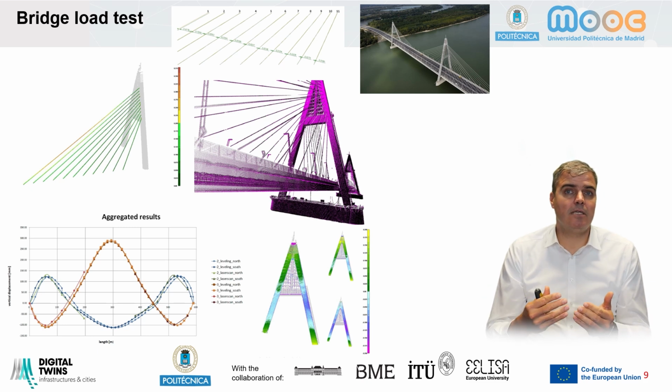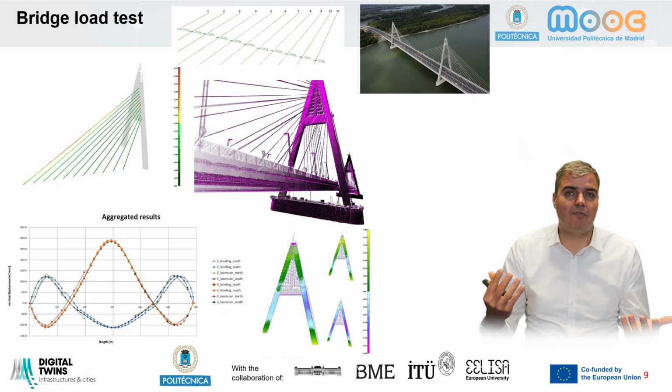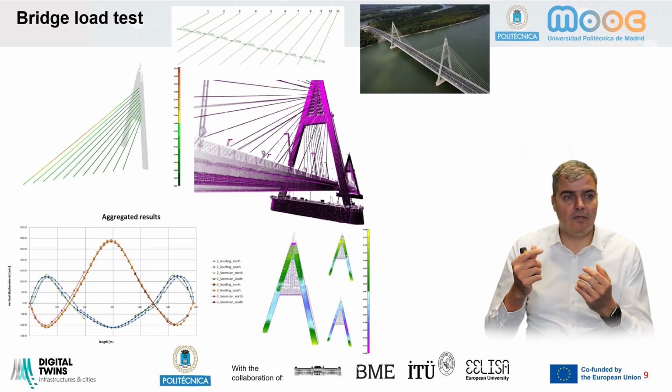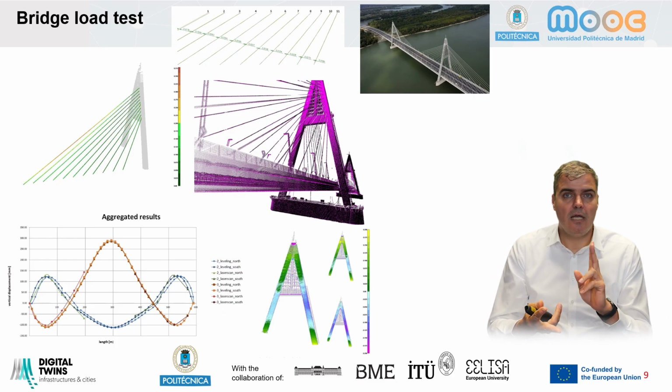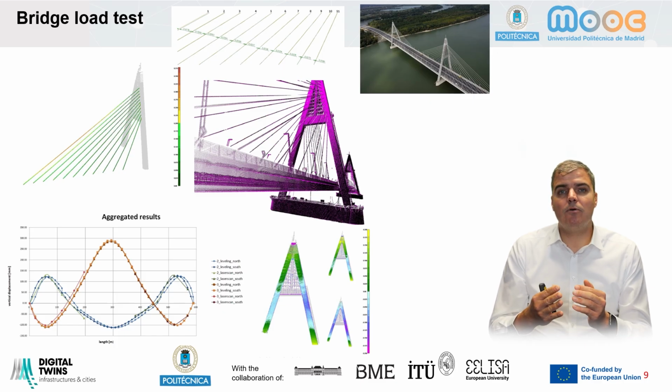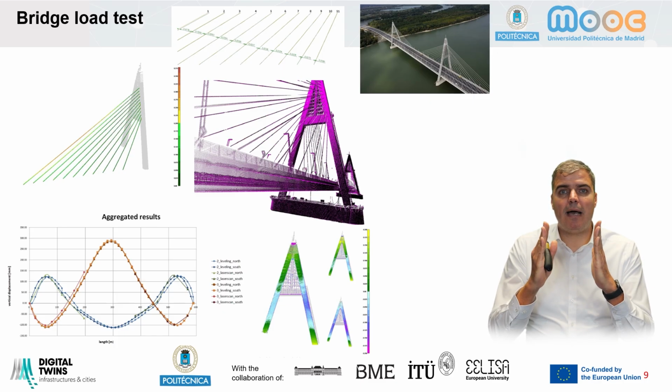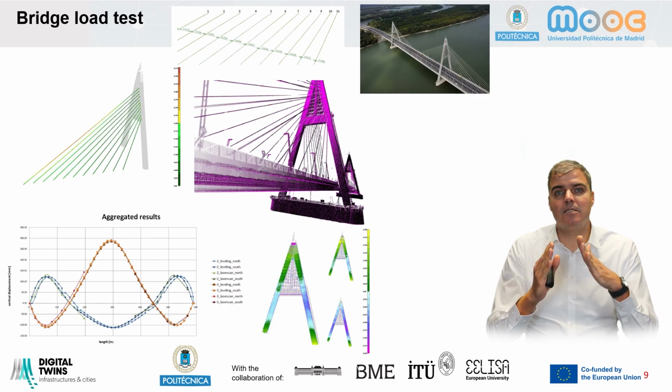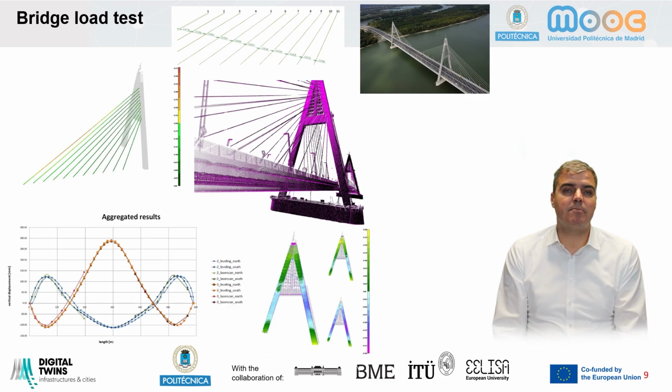And since we are using a surface-like technology like laser scanning, and we capture the entire surface of the bridge, combine the pylons, the cables, the pavement, the girder, all the structural elements, we could analyze not only the movement of the pylons, but the deformation of the pylons, the movement and displacement of the cables. So we provided a much more sophisticated and detailed analysis compared to the traditional surveying methods when we're measuring displacement in discrete points.